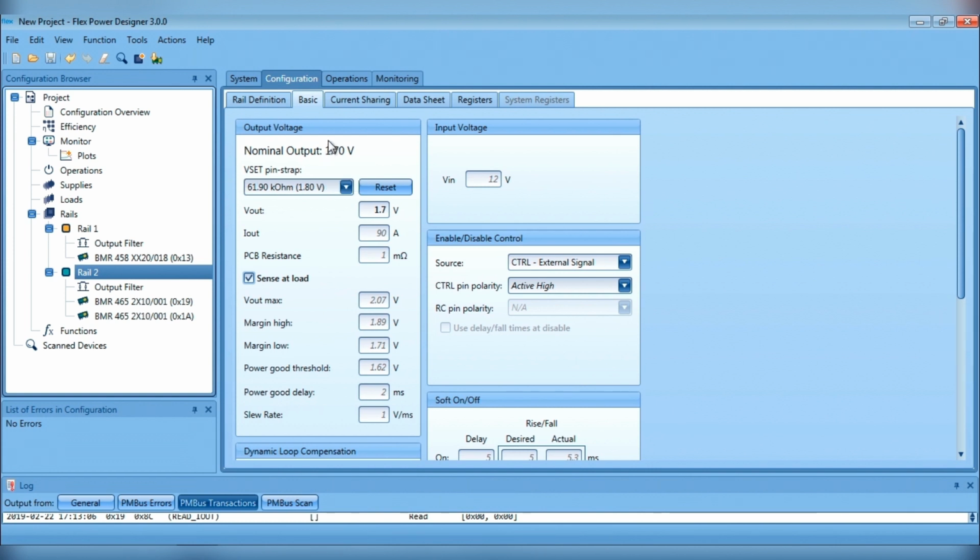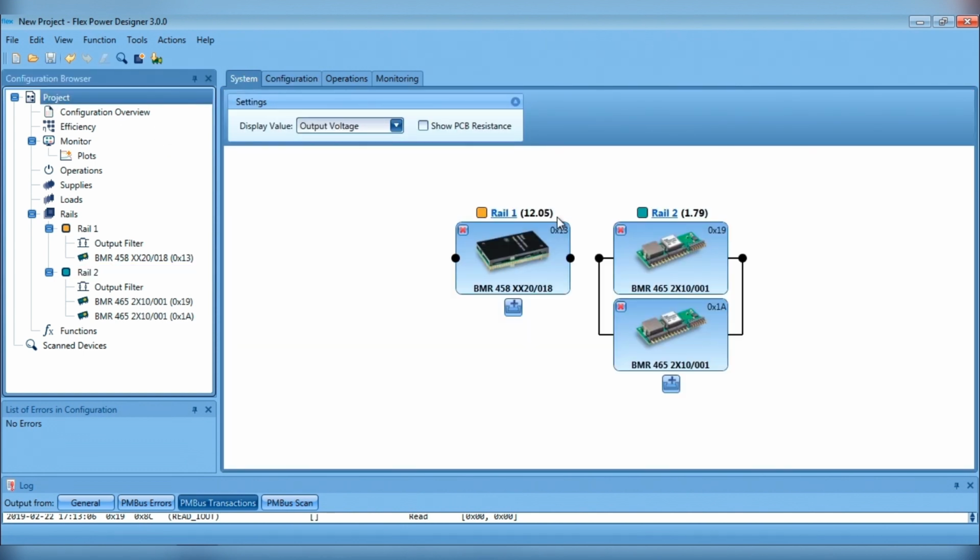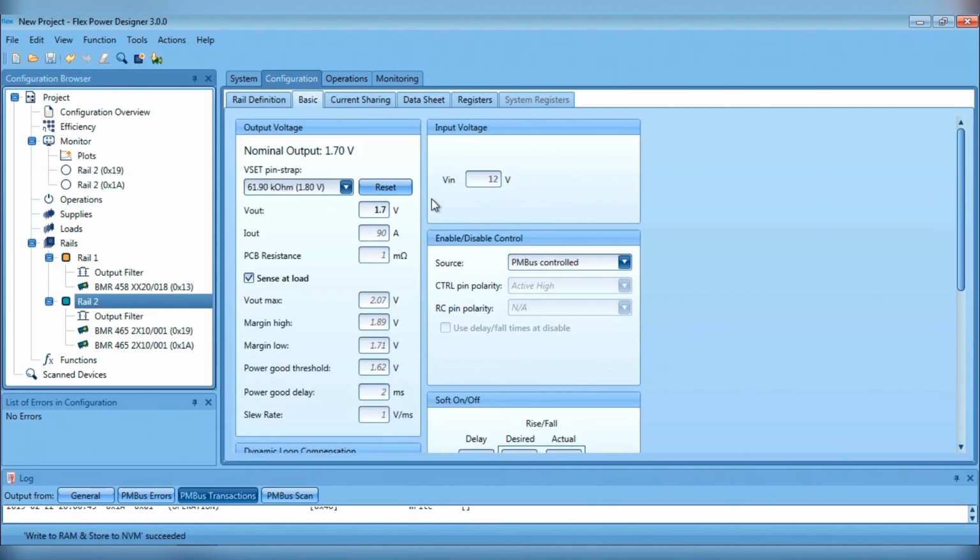So going back to the system aspect, I want to show that this is now showing up as our parallel devices in our power system. And if we want, for the sake of sketching out the whole system, we can connect this to here just to show that this is how our system is actually working. It's a way of building the model of our whole system, which will be useful for simulation or making sure that the input voltage for these guys is set to what is the output voltage of this guy, of our IDC.